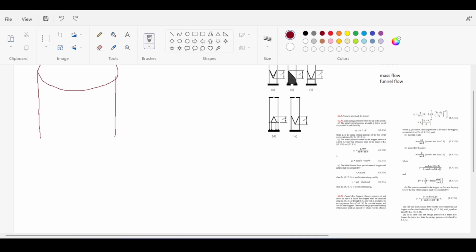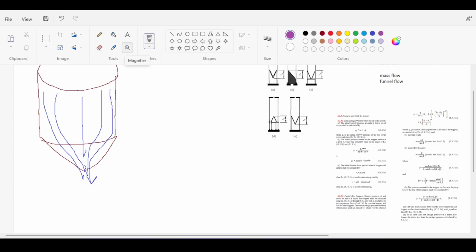So, okay. Since we have an opening below the silo, this means we need to funnel our material into this opening. Let me just draw here a circular funnel, which means that we are going to funnel our material to basically flow from top to bottom like this to get out of the silo. Of course, there are different flows here. Each material has to flow differently, and they soon exit the silo. This is how material would move in a silo. And such movement patterns would change different pressures in this silo. So it's a little bit more technical and more tricky than you thought. It's not just liquid that is getting out of the silo, but it's granular material.